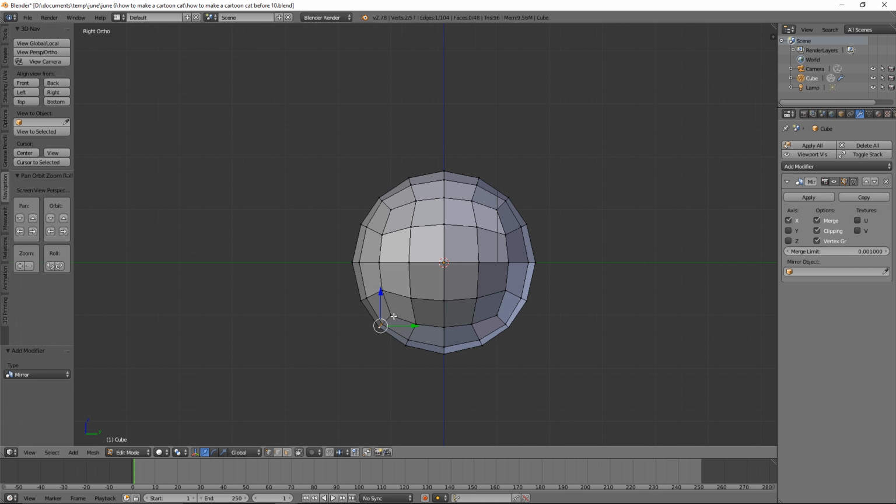We want to be able to affect, for what we're about to do, the vertices, edges, as well as faces around this geometry. So what we're going to do is press O. And when we did that, this blue circle lit up. We turned on our proportional editing tool. So when we press G, which allows us to grab these 3 vertices and move them, we can see this circle of influence for our proportional editing tool.